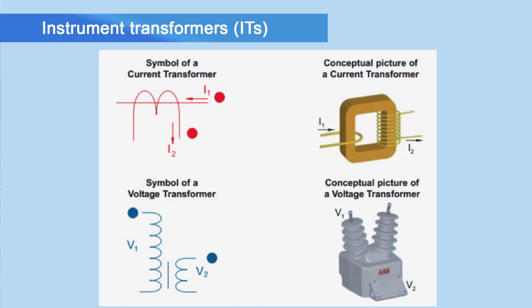To explain the basic working of the instrument transformers, there is a figure. In this figure or diagram, it shows the basic usage of instrument transformers. Mainly they are used to transform the primary voltage or current to values that are suitable for measuring instruments such as voltmeter, ammeter, wattmeter, energy meter, power factor meter, frequency meter, etc., and protection relays and control equipment.